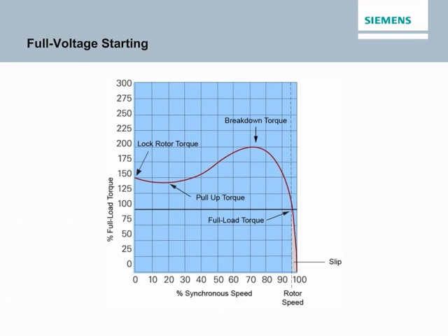When a motor is started with full voltage, starting current can be as high as 6 times the full load current for standard 3-phase induction motors and as high as 12 times the full load current for high efficiency motors. This high starting current causes power fluctuations that affect other equipment. As a result, many power companies require reduced voltage starting for large horsepower motors.